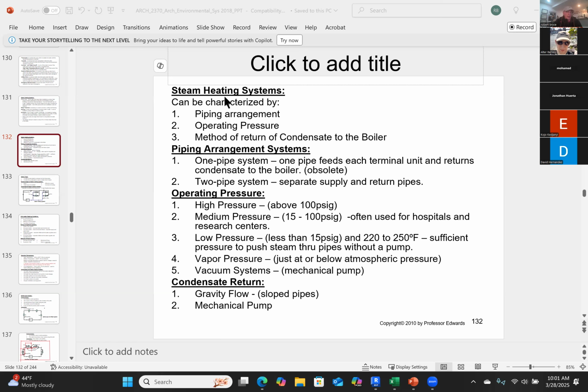And again, it's a change of state. And remember that every time we have a change of state, we either grab and hold heat, absorb heat, or we expel it. And so when the steam is in the facility at the area where we want to expel it, we convert it from steam to water, change of state, and it expels the heat that's embedded in the steam.